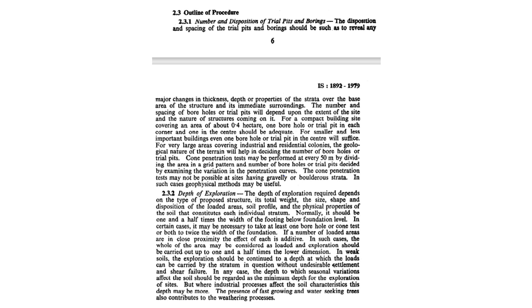So if his plan is ready, based on that, you will know which are the load bearing parts of that structure, or basically where the columns are coming, because columns are the load bearing parts of the structure, right? And columns will be resting on your foundation or footing. Okay, so wherever the columns are coming, it would be ideal to take one borehole under each column.